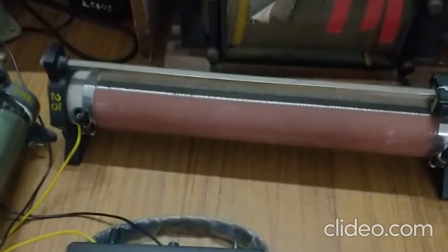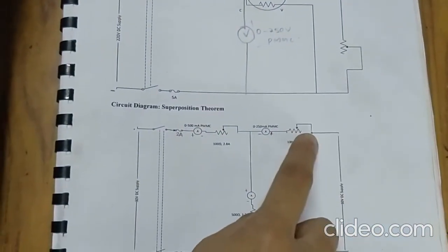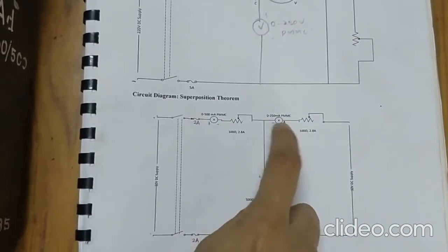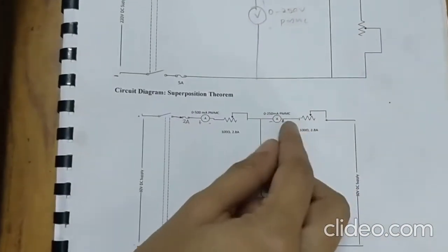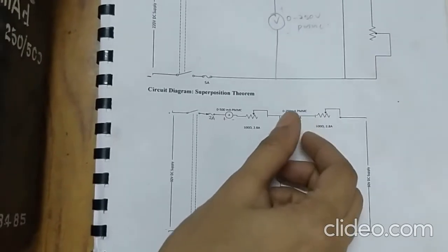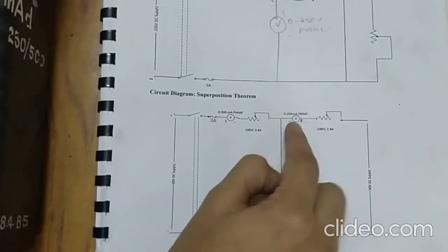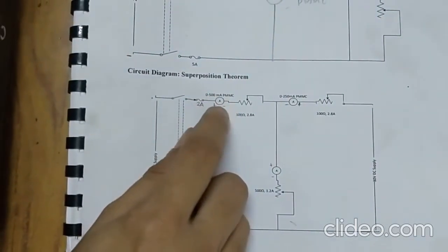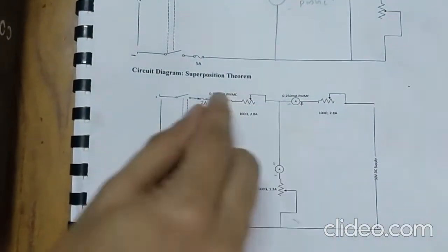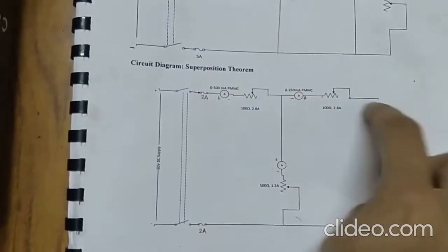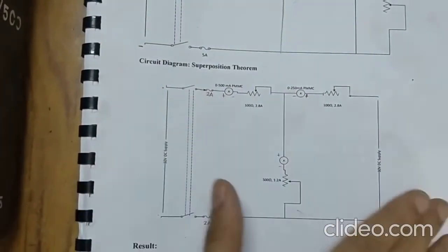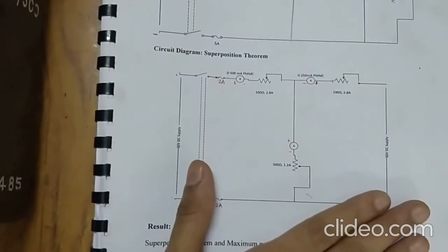While making the connections, you should be careful, because here, while we are giving 30 volt over here, the ammeter terminals will be positive and negative on these sides, which is the reverse of what was made in case 1. Here also the connection has to be changed. This terminal will be positive and this will be negative as the supply is from this side. So be careful while connecting the case 2 part of this experiment.